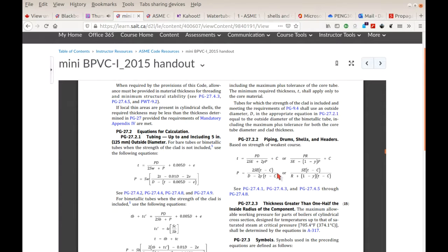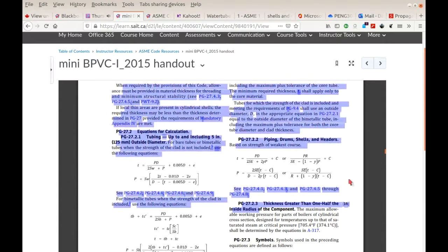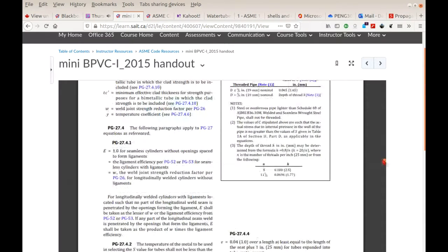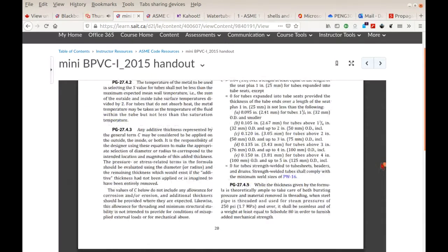Then the last thing is this letter C. And so let's find C. C is additional thickness. So where would you find something, Dave, that's over 480 degrees? Wouldn't you find that like inside the furnace somewhere? Water tubes or something? Remember that we're talking about mean wall temperature.